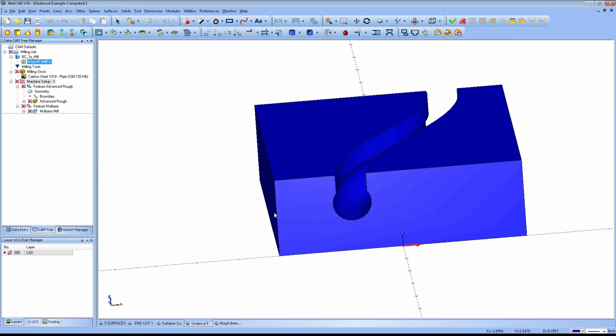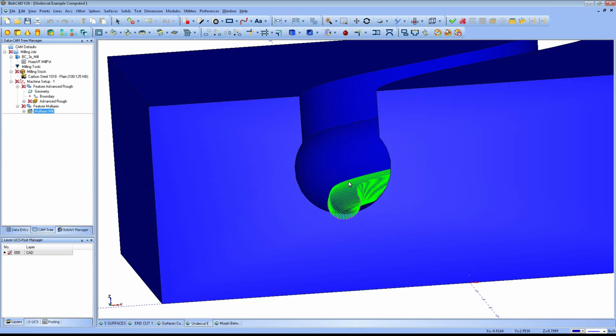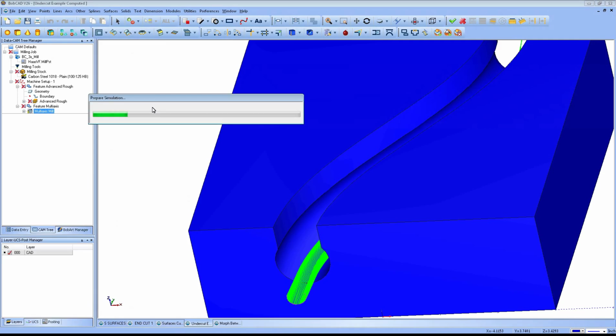The multi-axis output as a 3-axis toolpath will allow you to do undercuts. And let's do this one as an example just so you can see this type of a cut. So just to show you here the type of toolpath that we would be looking for, and you can see how it's curved, and that would be representing the shape of the tool. So I'm just going to run a simulation of what we're going to be achieving with this so you can see what we're working towards here at this one.